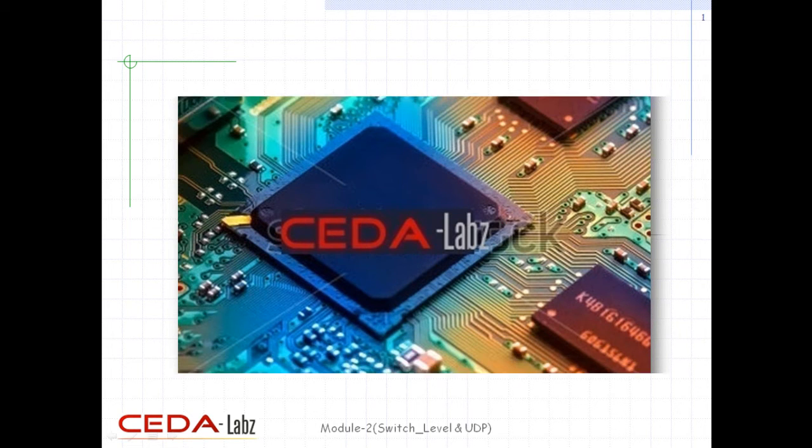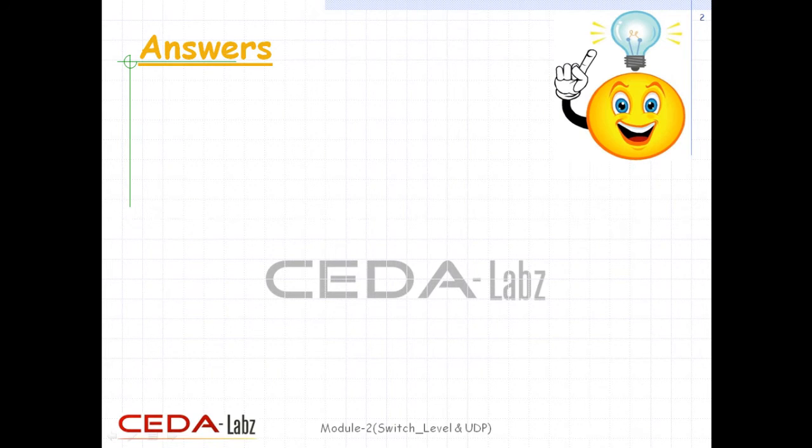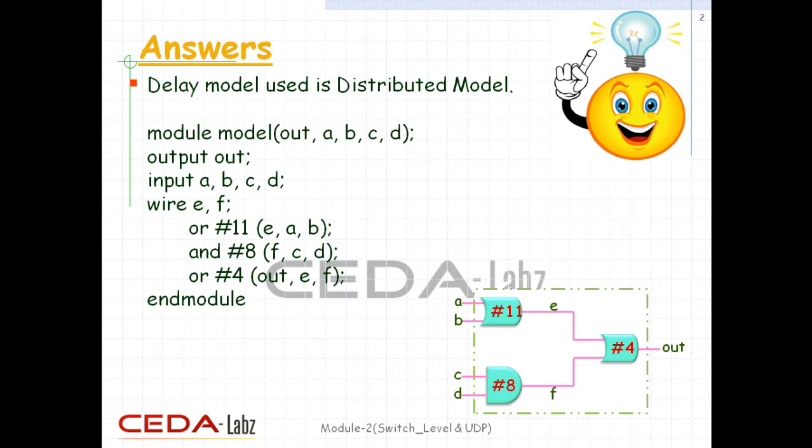Welcome to CEDA-Labz. First, let's answer the questions asked in the previous tutorial. The first question was to detect which type of delay model is used in this circuit. The delay model used is the distributed model, as delay is distributed to each gate. Secondly, we have to design this circuit in Verilog. Here is the code in gate level modeling with delays.